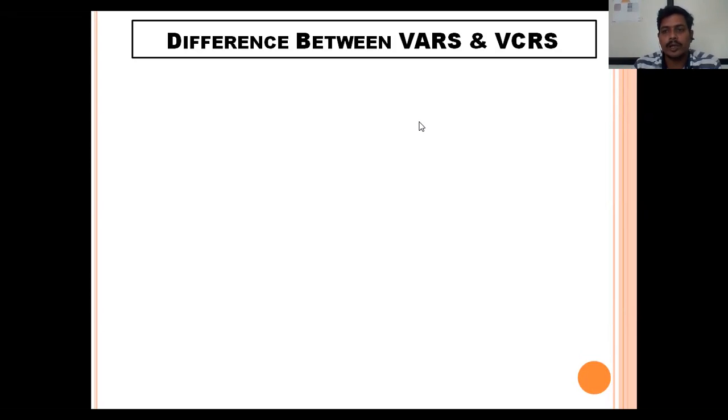As we know, when we replace the compressor of the vapor compression refrigeration system by an absorber, pump, generator and pressure reducing valve, then it can be called a vapor absorption refrigeration system. In a vapor absorption refrigeration system, the working fluids will be two. Out of that, one acts as an absorbent and another acts as a refrigerant. In the aqua ammonia vapor absorption refrigeration system, water acts as the absorbent, whereas ammonia acts as the refrigerant.